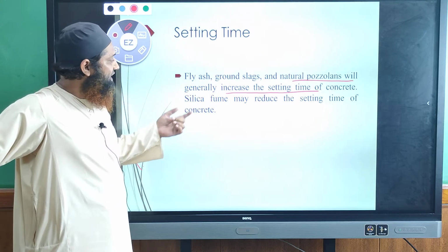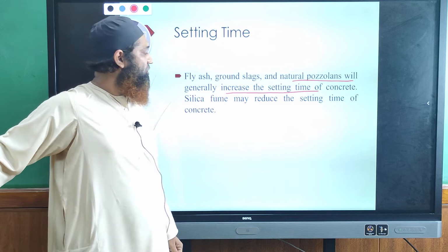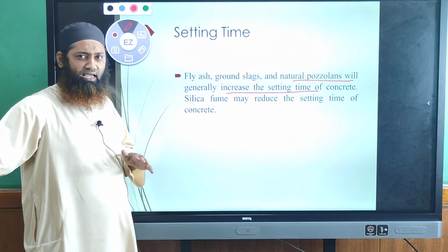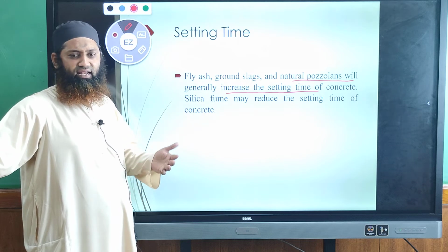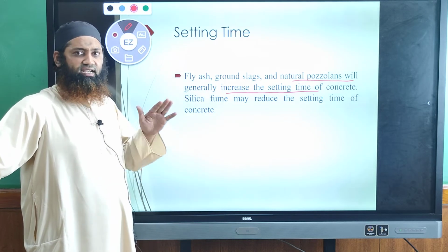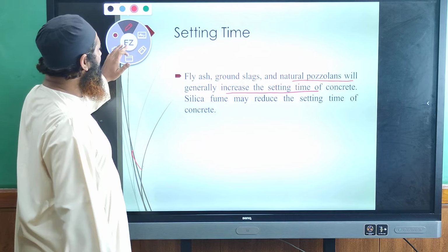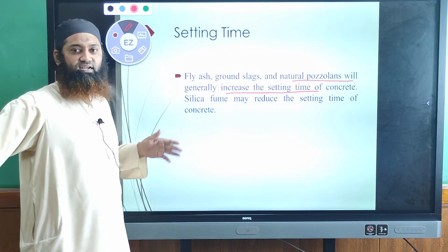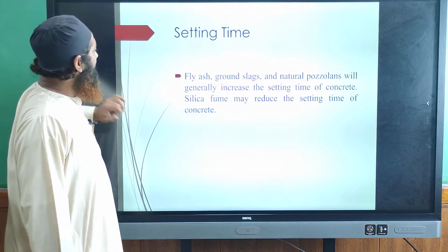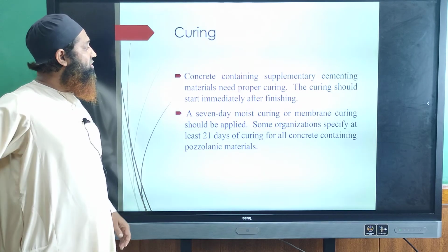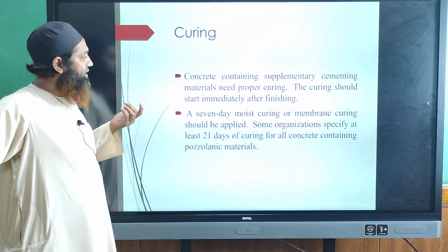Silica fume may reduce the setting time of concrete. So silica fume, sometimes it reduces the setting time also. Even this can be overcome by adding different materials where the setting time can be reduced here. So in terms of setting time also, these different materials perform very well. Let us see now about the curing. How about curing?